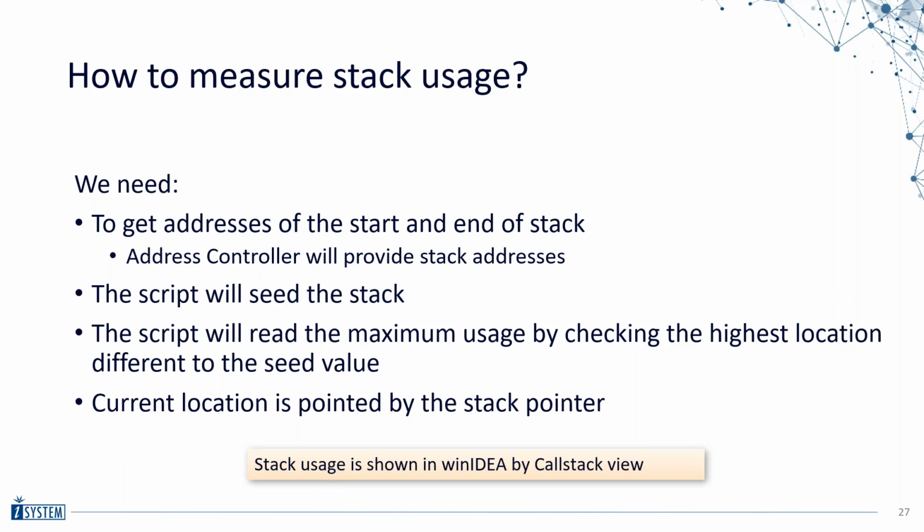We can modify scripts. If you have a real-time operating system, we can figure out what is the task stack. Of course, a lot of stacks have so-called stack measurement, meaning the real-time operating system structure has this information. Then we just need to read out from those variables raw memory. We can read from the structure what is actually the stack usage. We can have a different approach to control, to monitor the stack usage.